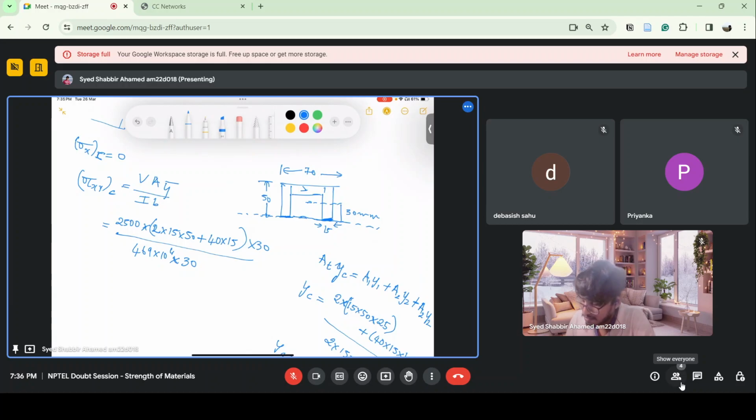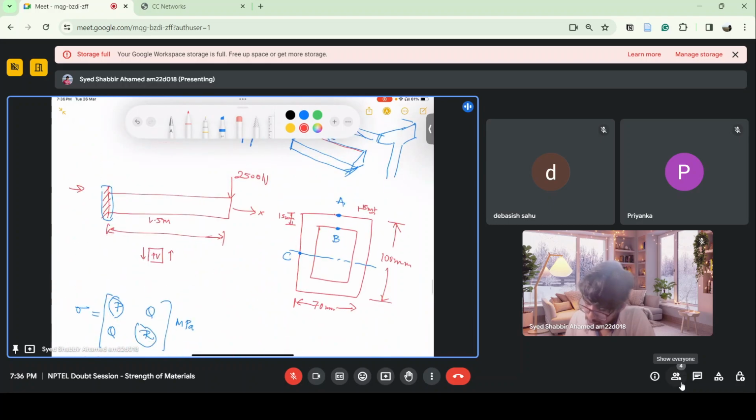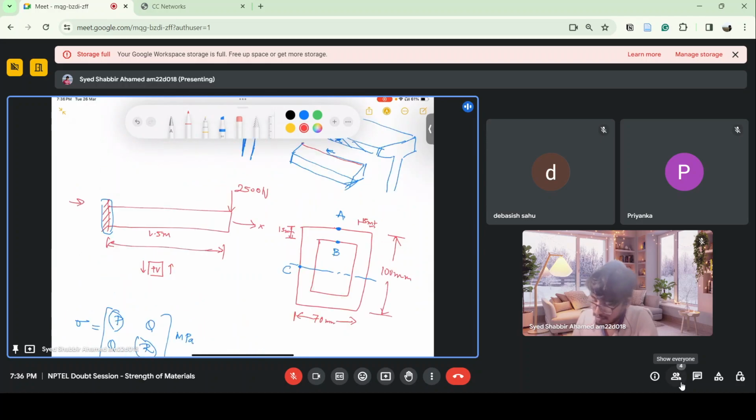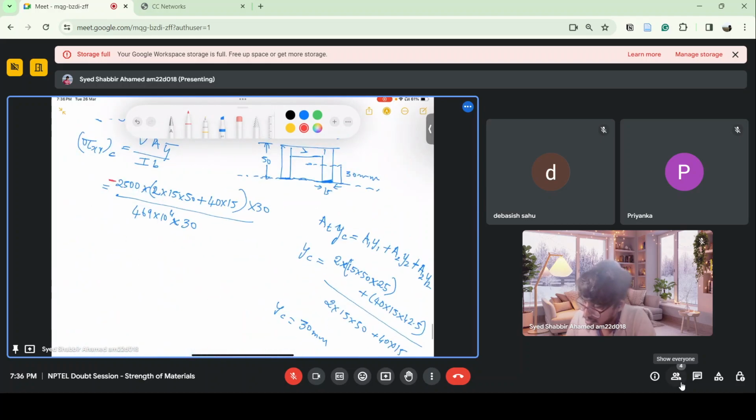So we'll get, so this shear force is negative actually. We forgot. You can see force is acting downwards, and according to the convention which we have seen, the shear force should be negative here. And that's why I get tau xy at C is equals to minus 1.1194 megapascal. This is the value of shear stress at this point.